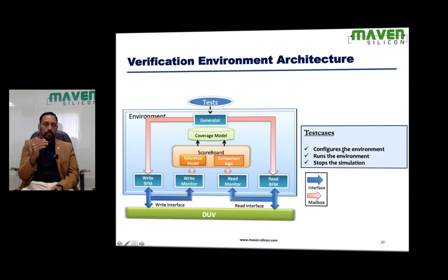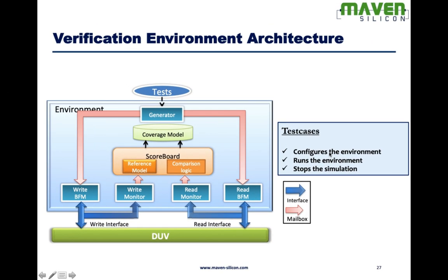Also, the test case is going to run the environment. Once it gives the command, the environment is going to do things one by one. Generator will generate the packet, the driver will drive the values, and the monitor will collect the packet. That's what's going to happen. So the test case is the one which is going to initiate the command. So it runs the environment. Also, when the data comparison happens successfully, then the test case is going to stop the simulation. This is how we create the reusable verification environment.